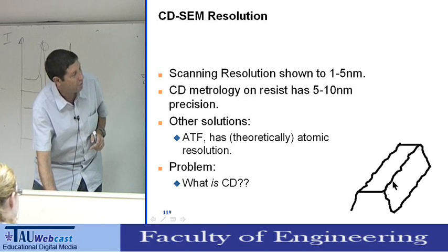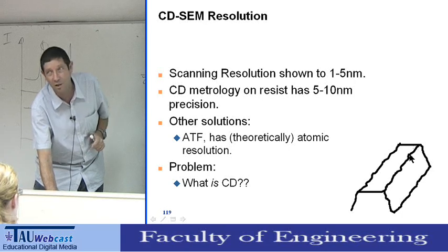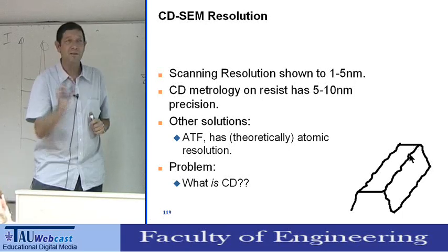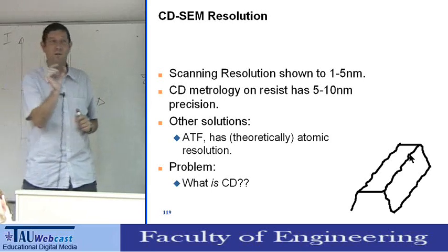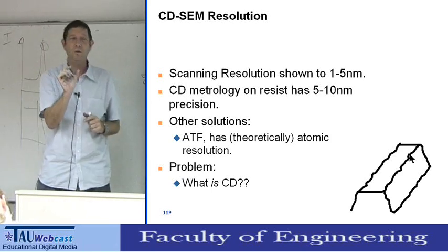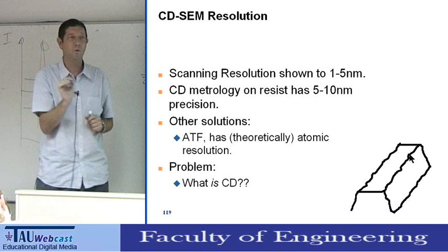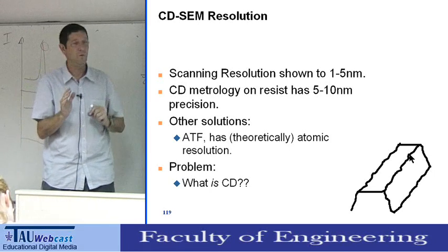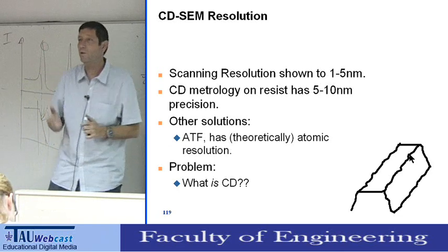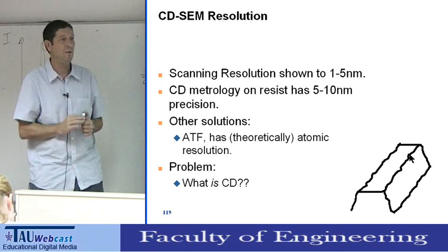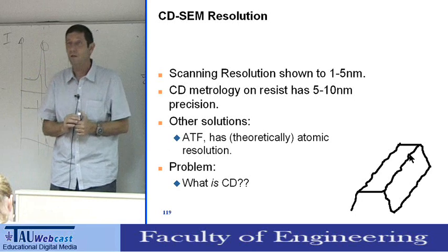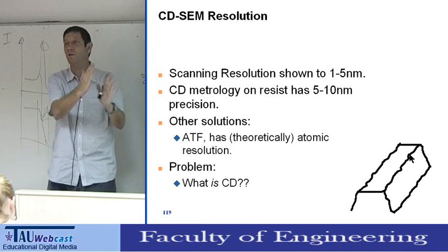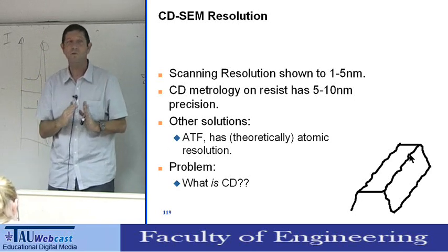When I actually took it from a real photoresist, we call this line edge roughness. The sidewall of the photoresist, if you go to very, very high resolution, to nanolithography, this is 32 nanometer, but if some of you are working on nanolithography, which is like 10 nanometer or 5 nanometers, then you find out that your sidewalls are not so smooth anymore because of a lot of problems.